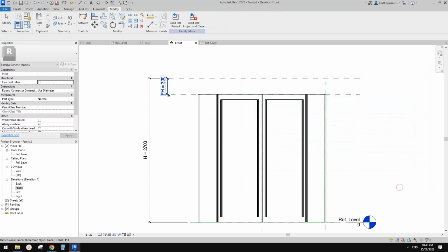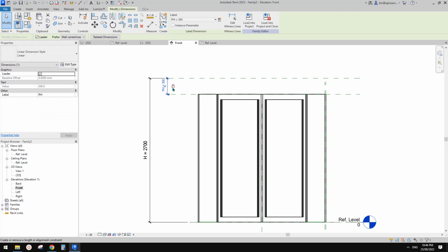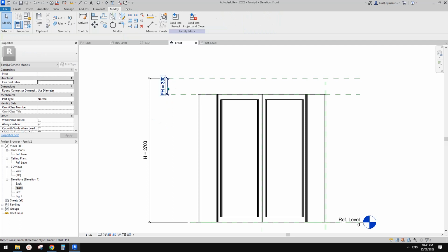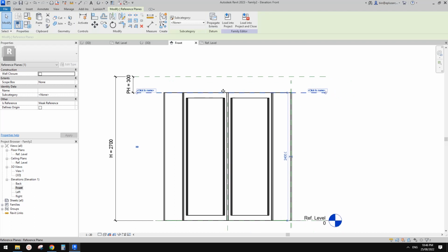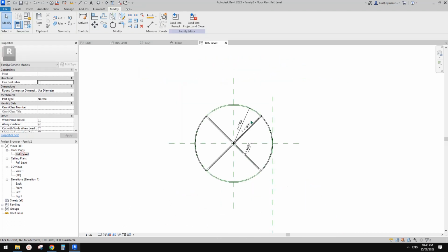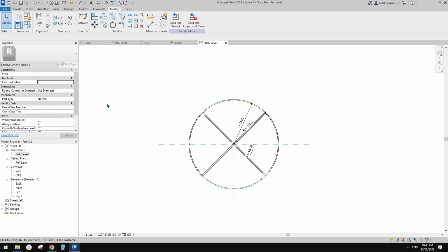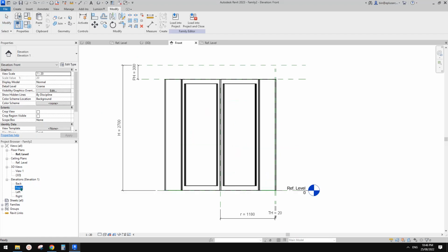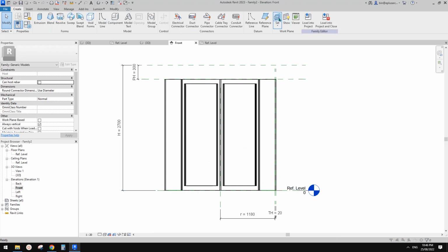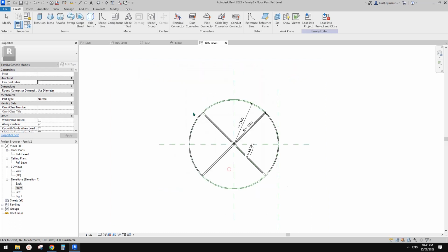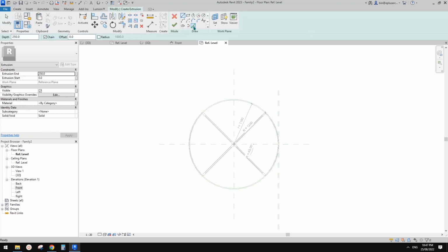parameters, so this one is relatively constrained, so it won't change unless it has to. Yeah, so that's probably it. Then we can just create an extrusion on the top. You can just draw it from the ground floor level and then drag it up, or you can just create a set work plane onto this reference plane. This way you will directly create an extrusion at that height.